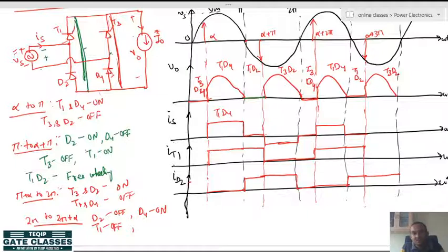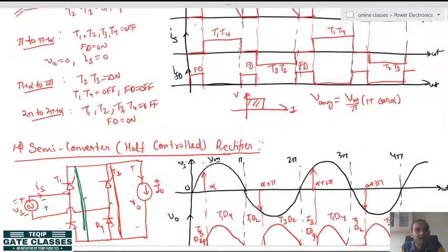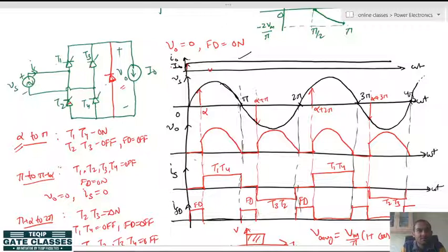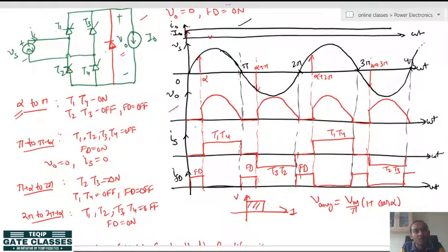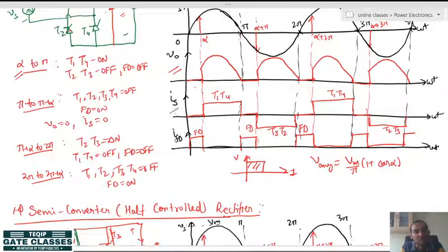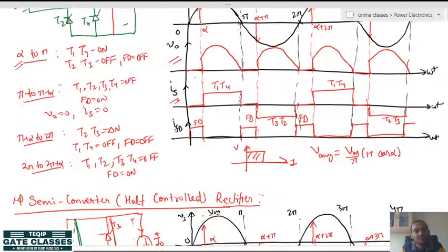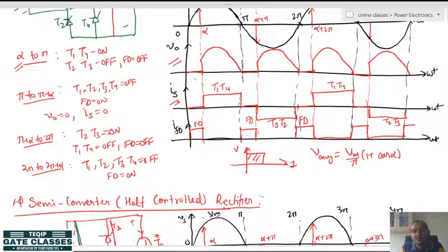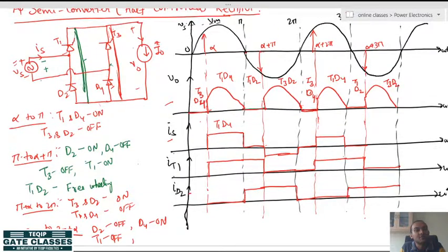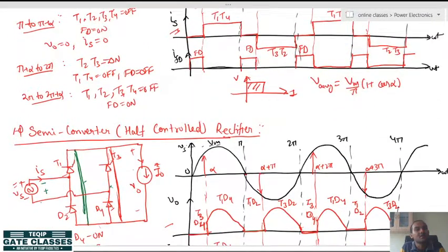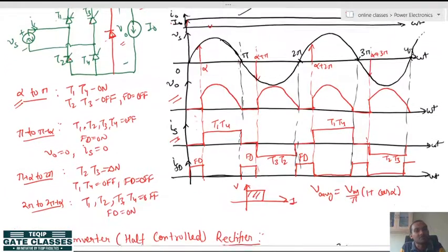Now you observe here, let me draw the D2 also. So, in this circuit what you have observed, in this above circuit where we have used the freewheeling diode, in both the circuits the output voltage shape was same and source current shape is also same. You see carefully, output voltage shape and source current shape, both are same, but still you see the major difference in the current or the utilization factor of the switches.